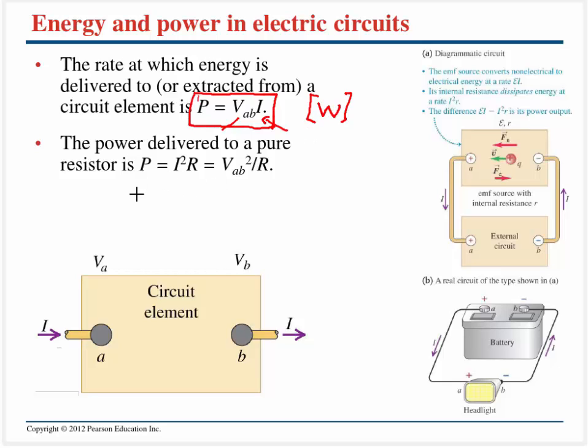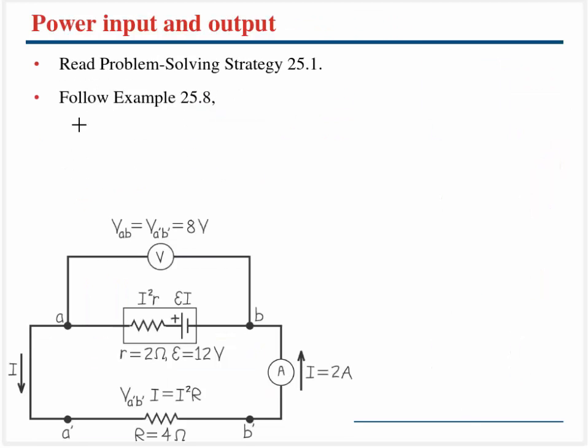If we're talking about a very pure resistor, also could say a very ohmic resistor, we could use Ohm's law and say V is equal to I multiplied by R to write the power as such, or we can rearrange it in the language of the current and write it as the voltage squared divided by R, whichever is most convenient for us.